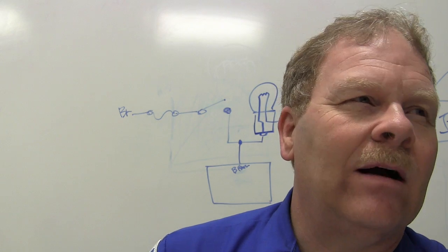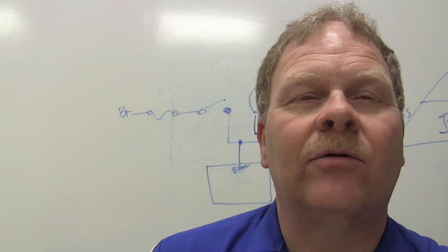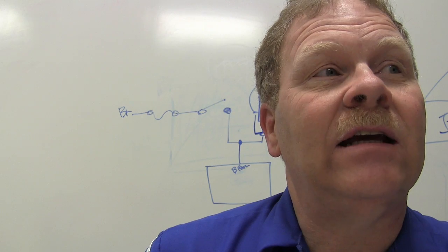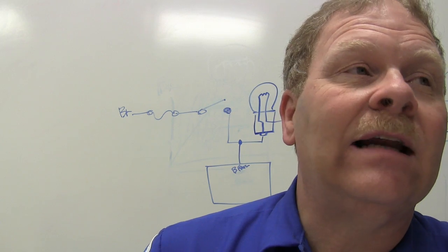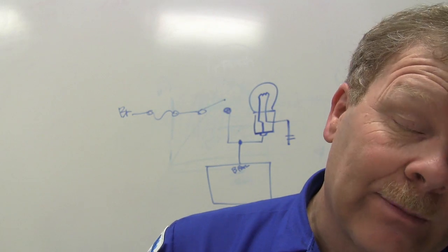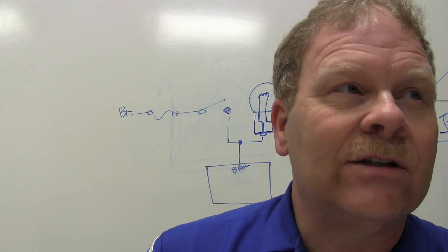We actually put an ohm meter on it, set it on the 20,000 ohm scale, and it was reading 1,050 ohms. And we heated it a little bit with the heat gun. We didn't have to heat it much. I had a heat gun on it at a distance of about 3 or 4 inches away, and I heated it for something like 20 seconds, and it opened up. So we know that sensor's bad.